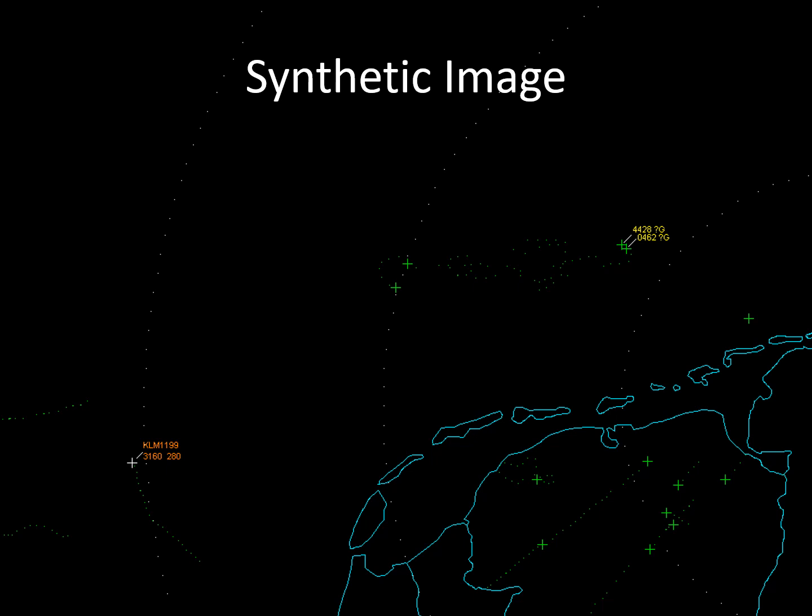Each current location of a target is a plot. This term comes from the earlier plotter, the person who drew these target signs on a planchette. New plots are linked to the older plots to form a track. Older plots of this track are displayed as a dotted line behind the current plot as a slowly fading history. A small bright line at the symbol shows the current course of the aircraft, which does not always have to match the history.